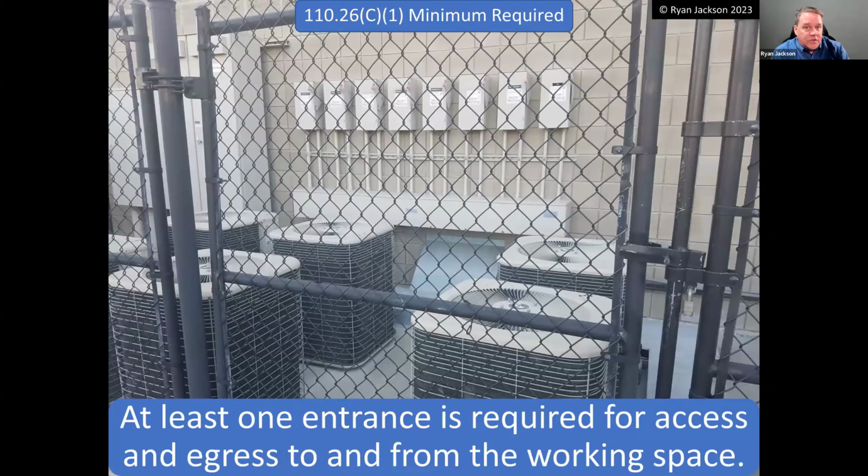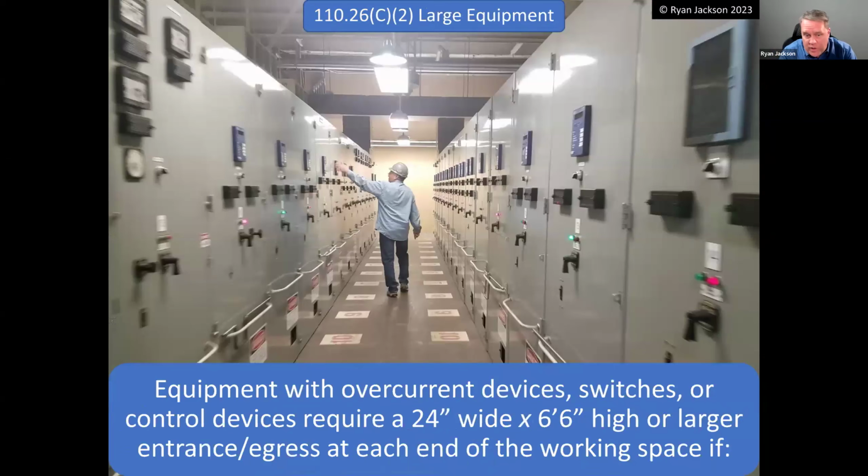Got to have at least one entrance to get to the working space. Makes sense. Here's my gate. That gets me there. For big equipment with overcurrent devices, switches, or control devices, you've got to have a 24-inch wide by 6.5 foot high or bigger entrance/exit at each end of the working space. What we do not want is a corridor like this that could have an arc flash and trap an employee there. Okay, so this individual needs to be able to get out of the working space on each end.